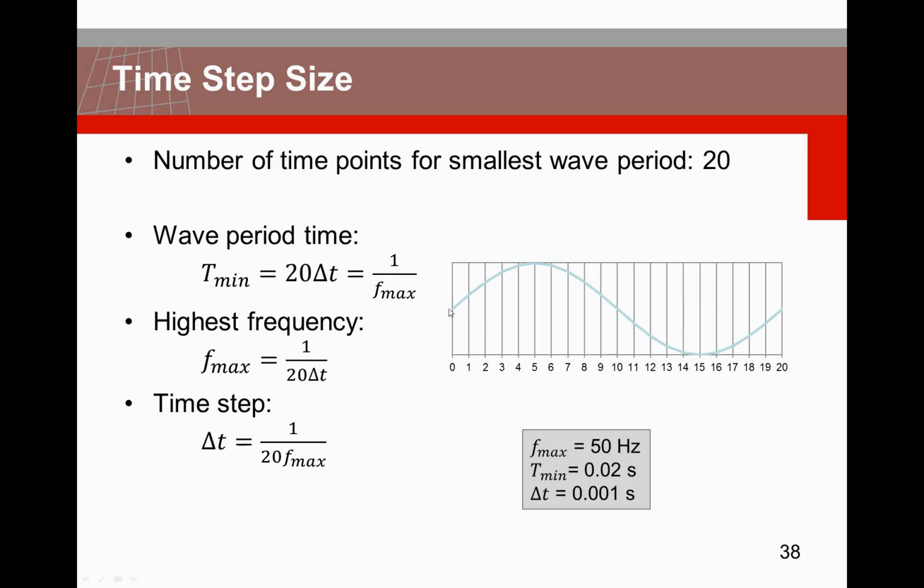What would happen if we did not choose, say, 20 time steps, but just 2 time steps? We would find 0 at 10, and 0 again at 20. It would give the indication that there is no wave occurring at all. So we need our time steps sufficiently small to nicely see the response at a certain point in time. Also here, as a guideline, we want to use at least 20 time steps to represent one period